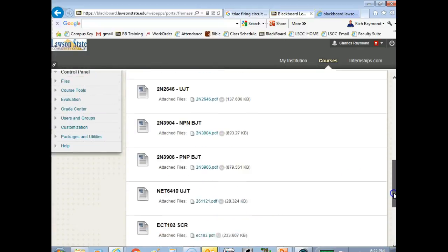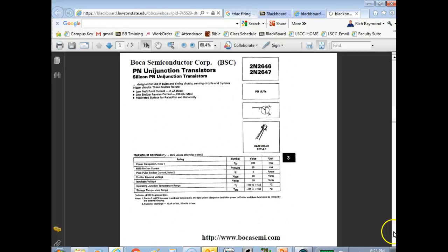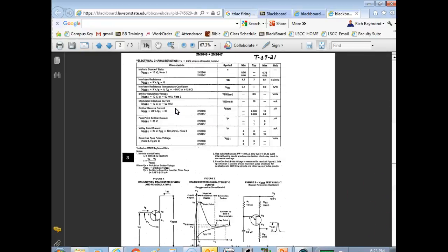And I don't have any triacs up here. I do have a UJT. So this is the symbol for a UJT. And there's a math formula. I don't know if it's in your book or not. But we set this thing on a little RC time constant. And then when it gets up to a certain voltage, it's going to fire, pop. And then it discharges the capacitor, and then it turns off. And then what does it do? Wait for it to charge up again.